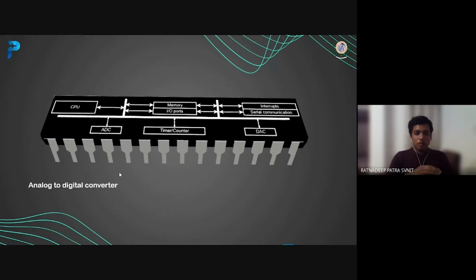So the maximum input voltage that this ADC can take is 5 volts, and the maximum output it can give is 1023. So we can say that 5 volts is analogous to 1023. For any other input voltage between 0 and 5 volts, we can calculate its output using the unitary method. Like if 5 volts is 1023, for example, if the input voltage is 2.44 volts, what will be the output? Using simple mathematics, we can calculate that it will be 500. So this is how the ADC works.